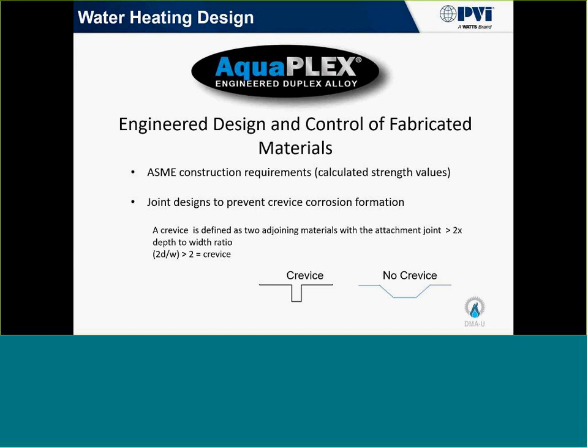So with regard to that, there are some manufacturing practices that need to be taken into consideration if you're going to be using this type of material. You have to be able to weld it. You have to be able to work with it. You have to be able to passivate it after it's all done, and that's not an easy thing to do.